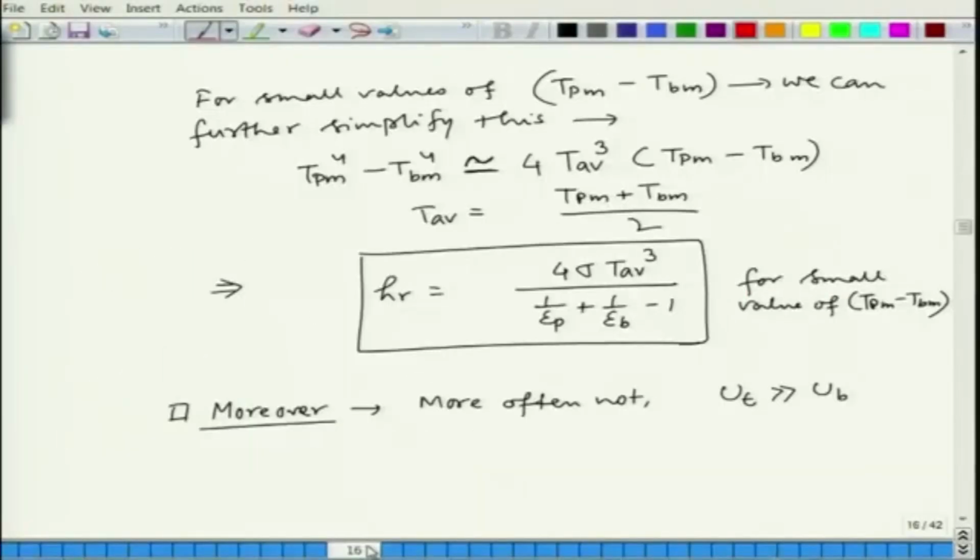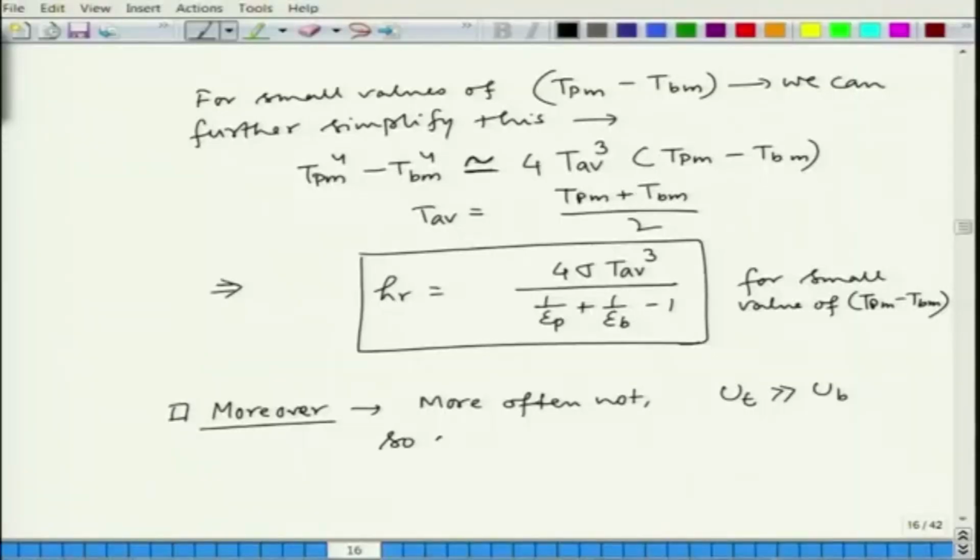And we cannot do away with the cover. We have to have it, and that is why the radiative and convection heat losses are also happening. So, we cannot do away with it, and that is why we are stuck with UT, but UB is in our hand. It is the thickness of insulation we can increase, and often it is negligibly small. So, often UB is completely neglected.